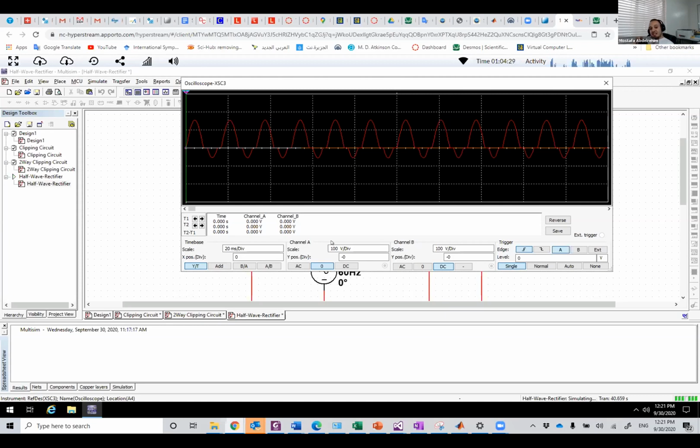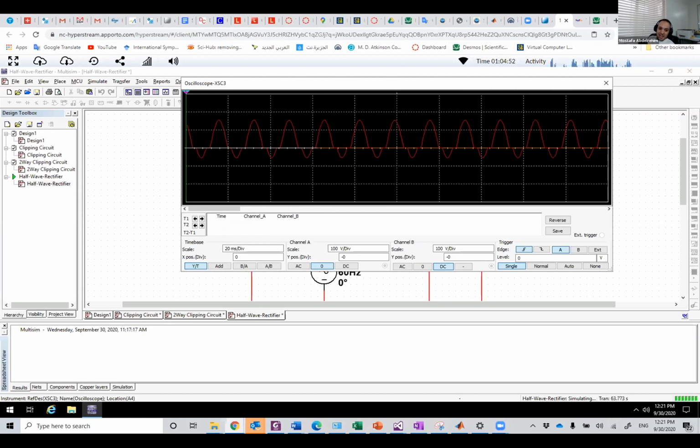Once it clips, the voltage on the diode is constant, equal to minus 100, the breakdown voltage, and the rest of the voltage, because Kirchhoff is always applicable, goes to the resistor. So the resistor, which is the load that's supposed to have only positive voltages, now receives some negative voltage. Even the 50% rectification has gone now.